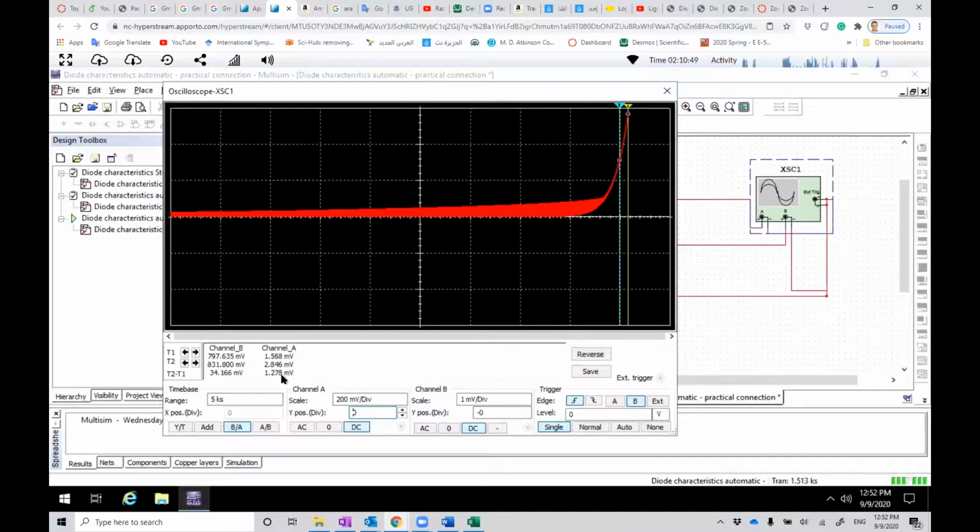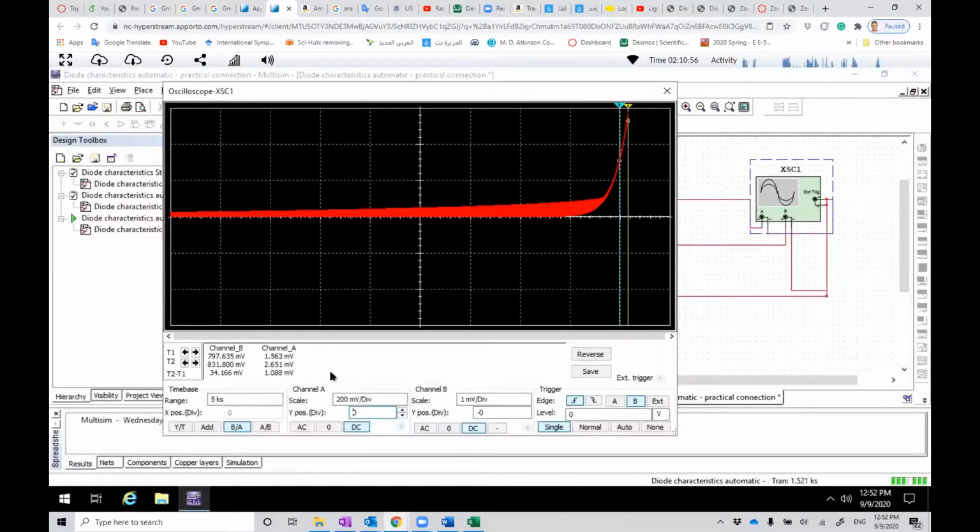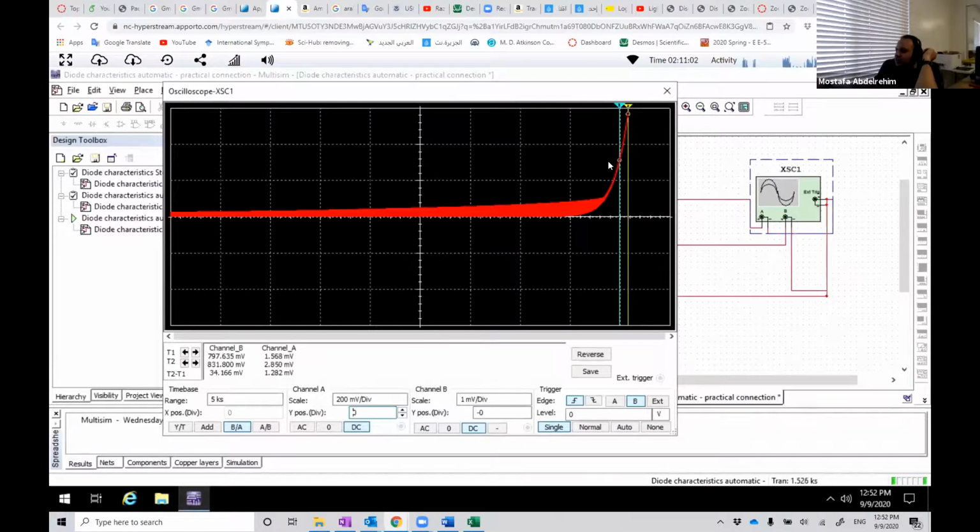So why can't we use find slope? Or why wouldn't that work? Where if we did y2 minus y1 to get the slope. Yeah, so this is what I'm saying. These 2 markers, they confuse me, especially in XY mode. So I'm not using them. But anyway, here you have 0.19 divisions. So you should multiply this by 200 millivolts.